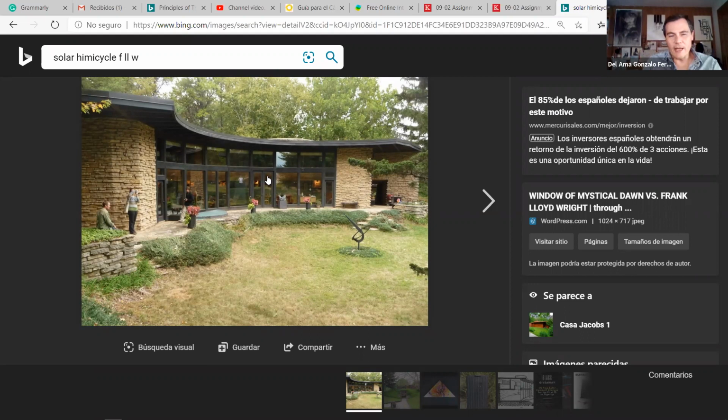If we are designing houses in cold climates, there are things that have to do with thermal insulation, with materials, air leaks. Those are building science issues, but the main issue is the design. If we design something that is good from the beginning, we have a lot of things solved. Basically, we need to know that we can make the most of the southern sun, and we need to place small openings on the northern elevation or facade. Okay, let's go back to the lesson.